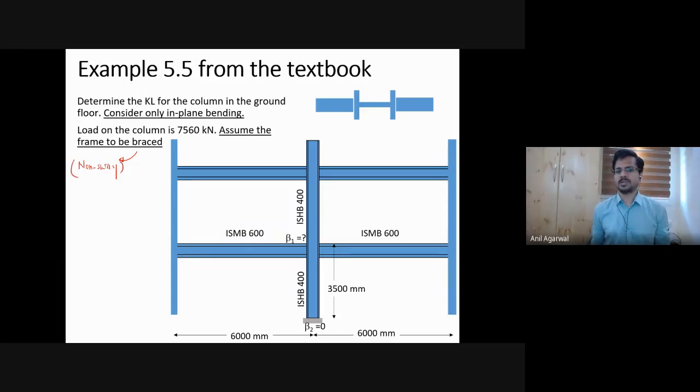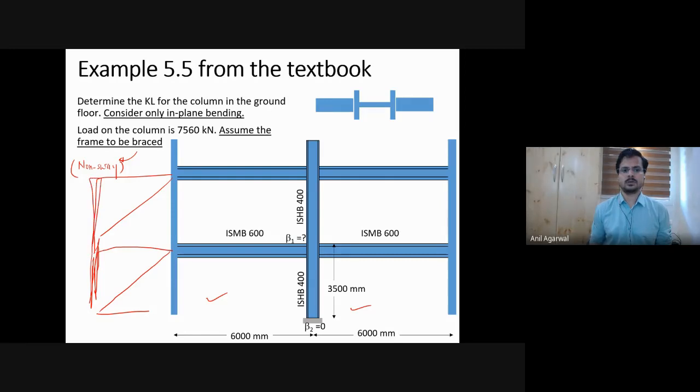Good. So how do we make sure that it is a non-sway frame? Probably what is happening is that somewhere at one of the bases, so these are the two bases shown to us, but this building must be extending, and somewhere down the line I may have some kind of a bracing system in this building to restrain the lateral movement of the building. Then this kind of system will provide you a non-sway behavior. Or otherwise, if the beams and columns are very heavy and you put them as a rigid connection, that also can be used.